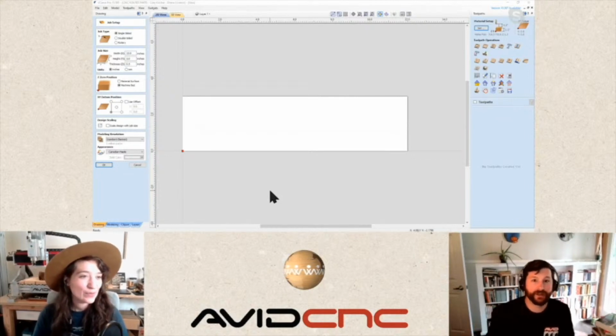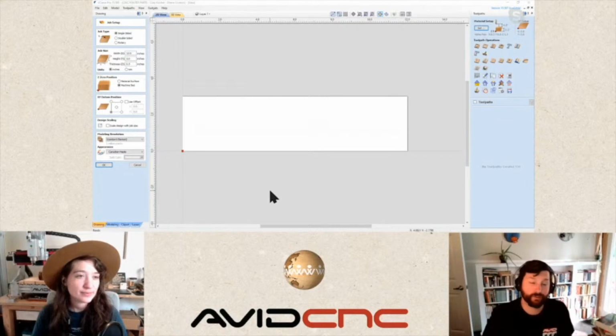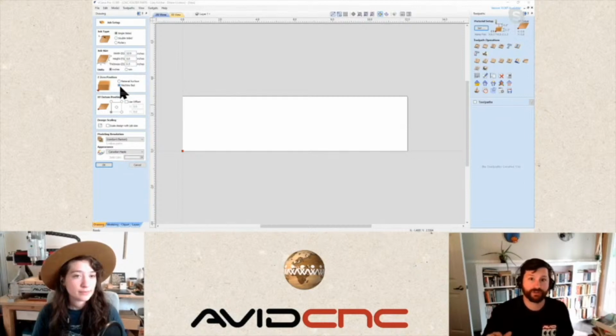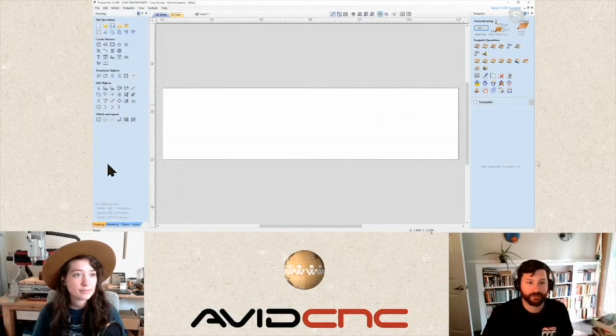We're going to start with a 12 by 3 inch blank that is a 1/2 inch tall. Right now we have this zeroing to our machine bed. Sometimes this can be really nice when you're doing surfacing or any other type of facing, because we are surfacing it to an exact height. We know exactly where we're getting to there. So we have a 1/2 inch thick material, lower left-hand corner as our XY datum. Perfect. So we have this set up.